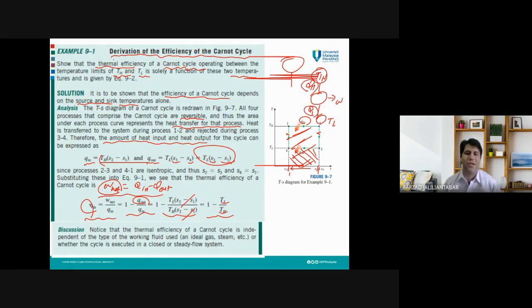How can we measure that? Which type of sensor will help us to measure QH? Ask yourself how you can measure the thermal energy which is transferred, the QH. It is not easy. Maybe nothing comes to your mind. How about TH and TL? It is temperature. How can we measure temperature? The answer is simple. We can use different types of thermometer. Simply, we can measure TH and TL by a thermometer.